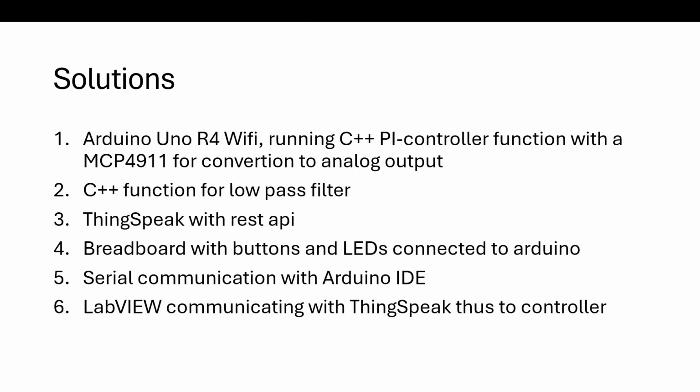Okay. The solution that was made is an Arduino Uno R4 WiFi running Arduino C++ code, specifically a C++ PI controller and a C++ low-pass filter, with an MCP4911 DAC unit for converting from digital to analog output.